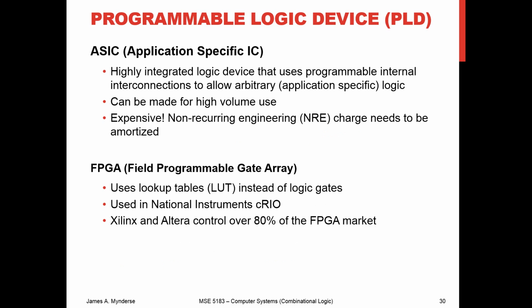And so if you think about these two, well, I guess I'll talk to you about the ASICs and the FPGAs first. ASICs compared to a programmable logic device: an ASIC is an application-specific IC. That's where you've designed specifically for the task that you are dealing with. So a PLD is more of a general structure that you could set these fuses within in order to adapt it to your particular design. An ASIC would be if you designed specifically for the one thing that you needed, which means that it's very efficient for that one task, but it means that it's expensive because I hope you're making thousands.